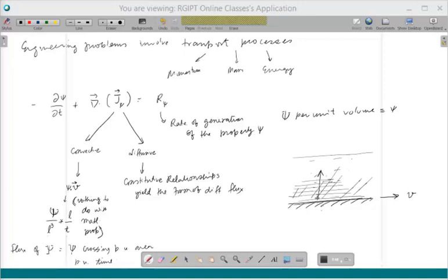So basically, this is a momentum that you imparted, and this momentum actually diffuses in the medium. The x momentum which you imparted on this plate is diffusing away. If you have two different materials, for example honey versus air or water versus air, the rate at which this diffusion occurs will be different. Momentum diffusivity in that case is the kinematic viscosity. We have all learned that. Kinematic viscosity is a measure of how fast momentum can diffuse in a medium.